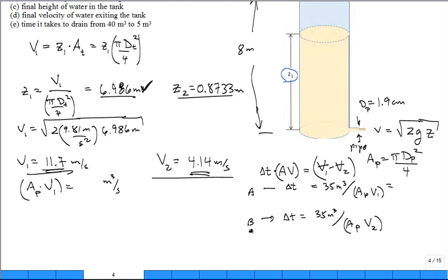You don't have to know the trust equation because it's published in some book somewhere, and you're smart. You're not smart like that. You've got to be able to do stuff on the back of the envelope. You've got to be able to estimate, like this is going to be a long estimate, delta T, the time to drain, that this is going to be a high estimate, or this is going to be a low estimate. What would be a better estimate? Estimate C, can you see what it would be?